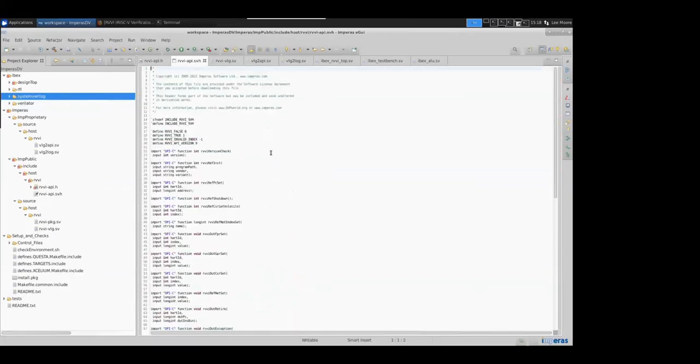And what we also have is a set of import DPI routines so that we can call those same functions from within a SystemVerilog environment, which is what I'm going to be showing here today. So for each of those API calls within the C header file, we have the equivalent here that is used within the DPI.